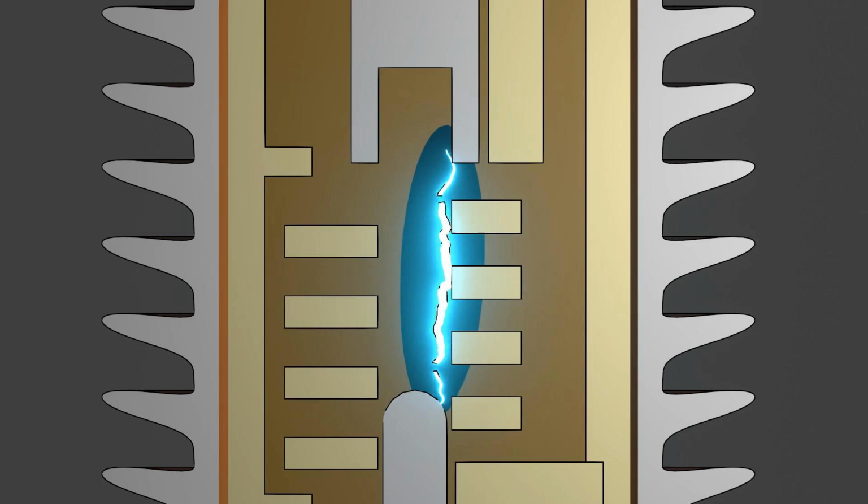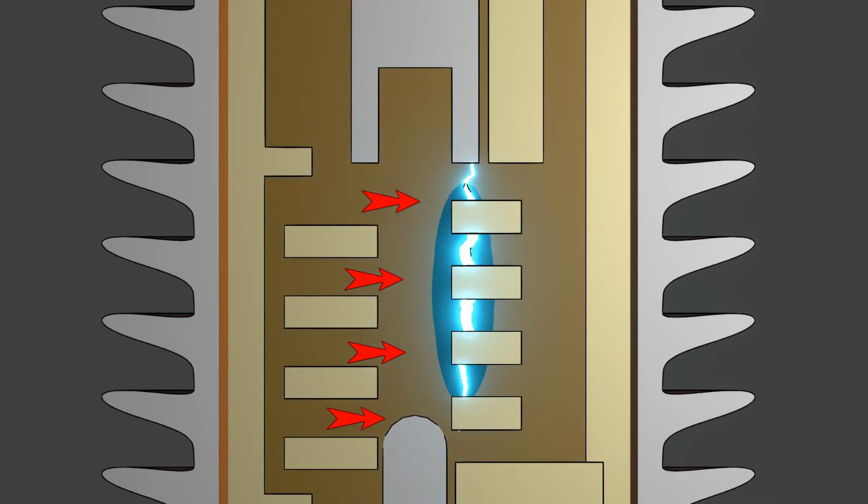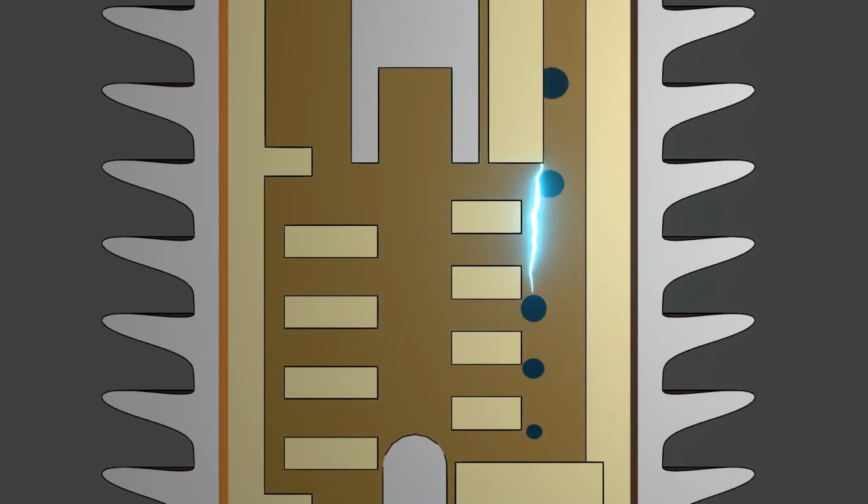When the vent openings uncover, these vents open one by one. The arc and the gas then get a path to exhaust. At the same time, fresh oil comes in. It occupies the vacant place through this path and fills the gap between the moving and fixed contacts. This fresh oil then pushes the gas outward through the vents. Ultimately, the gas bubbles rise upward through the bus and accumulate in the vacant space at the top chamber.